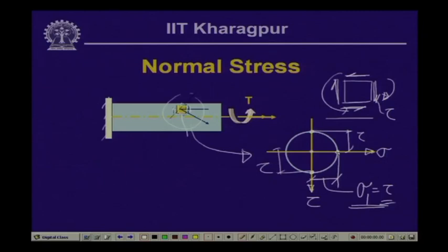Now, this particular point is at an angle of 90 degrees with reference to the reference plane. In the physical plane, if we move clockwise 45 degrees, since in the Mohr's plane 2 theta is 90 degrees, theta is 45 degrees, which is shown here. Perpendicular to this is the plane along which it will fail, and the direction of the normal stress sigma 1 is this.